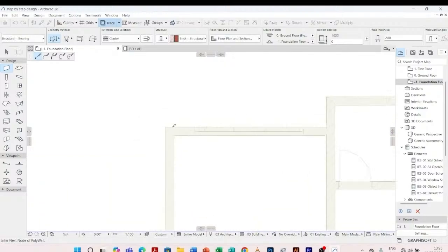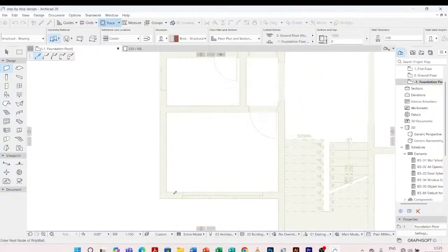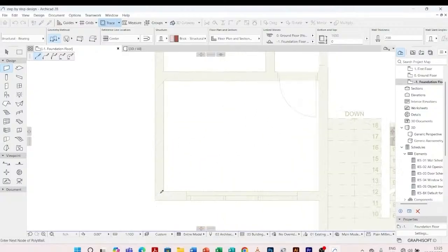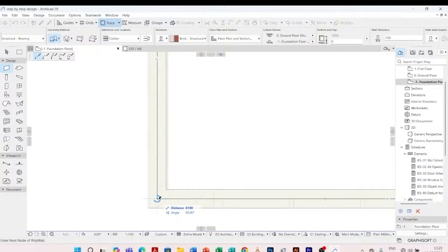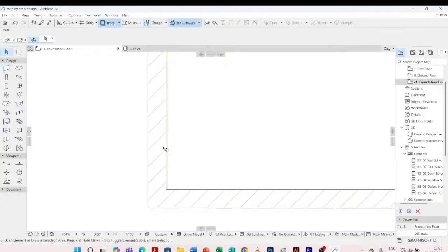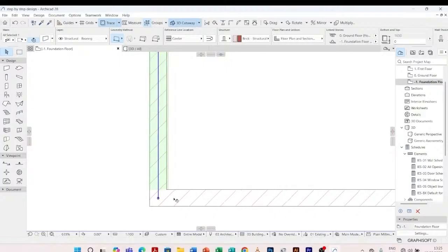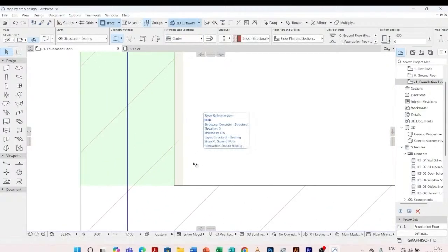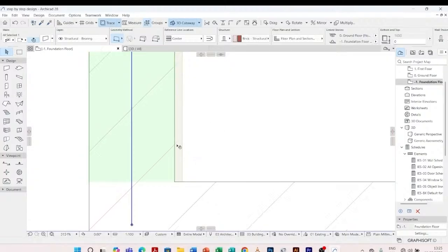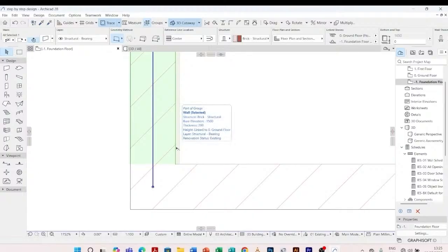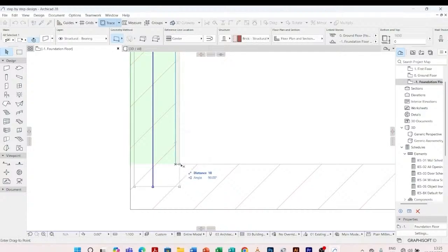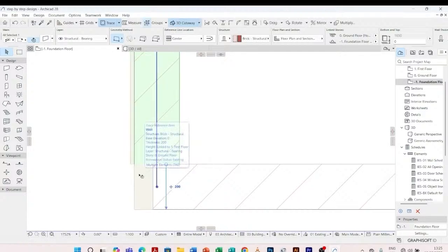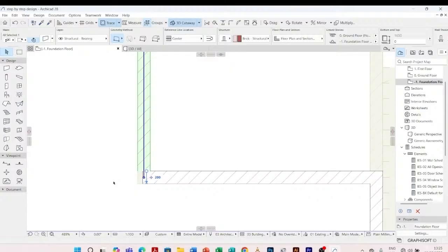You do this for all the walls. Hold on to shift. So we are going to move this one. It is not in line with the above wall. So you click or you type Ctrl D, that is for dragging. You come, you drag from this point to that point.